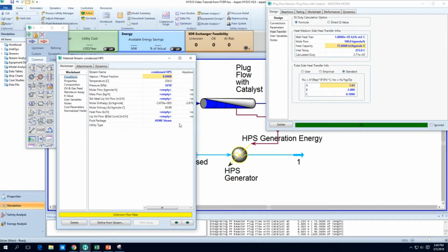Well, you can subcool it if you want, and I suggest subcooling it because there will be some temperature change along the way. So I'm just going to put it at 250. The reason why you subcool it is because there are pressure drops across every heat exchanger you go through. And with every pressure drop, there's going to be a slight pressure change, and with every slight pressure change, the temperature is going to shift down slightly.